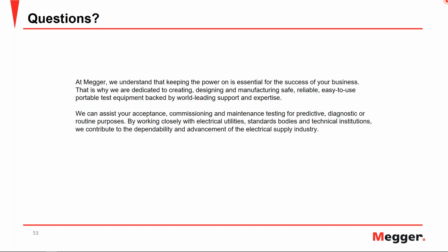High pot test is another one, and I'm not talking specifically about transformers, in general there are a lot of other methods available to check the condition of insulation. PD is another method that you can use. But the reason power factor testing is so popular is its ability to trend and analyze the measurement.